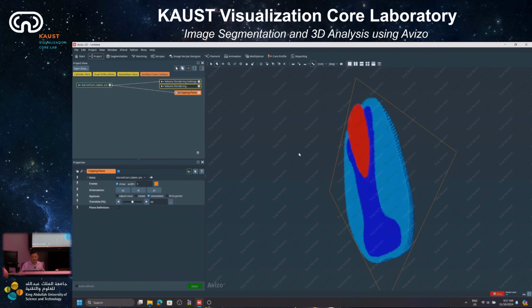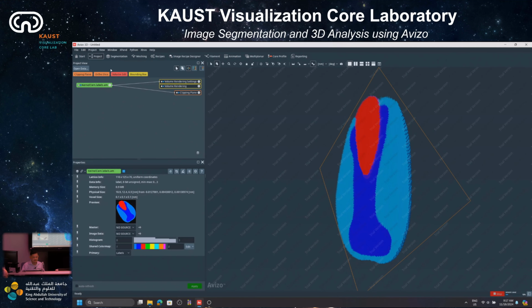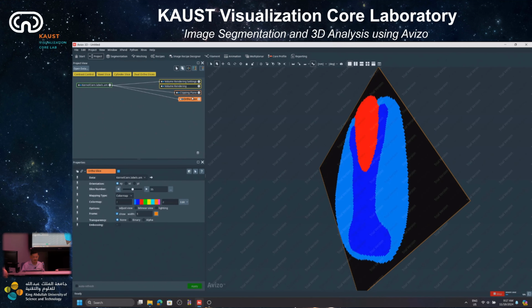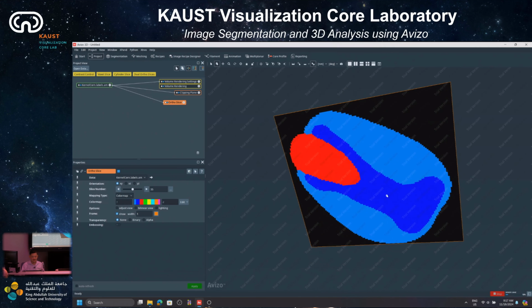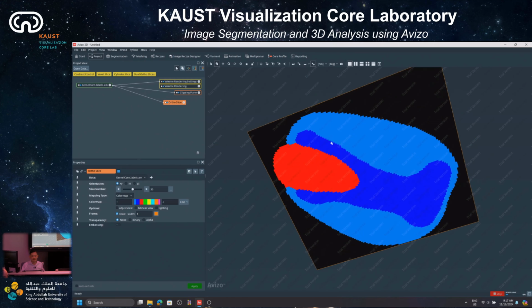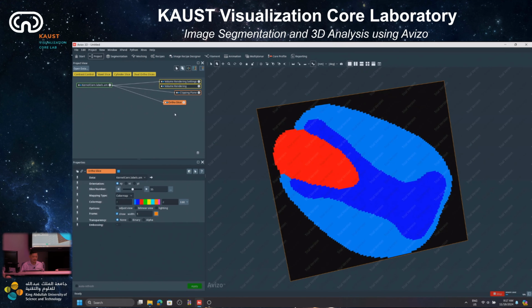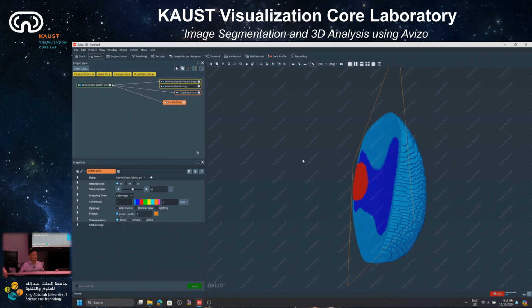The clipping plane, you can see it's just transparent clipping. But the ortho slice also shows what is in the ortho slice. You can see the background, everything is not transparent. You see the ortho slice clipping, the background by default is padded to 0 value, so it's black. But if you look at the clipping plane, it's just transparency cutting.